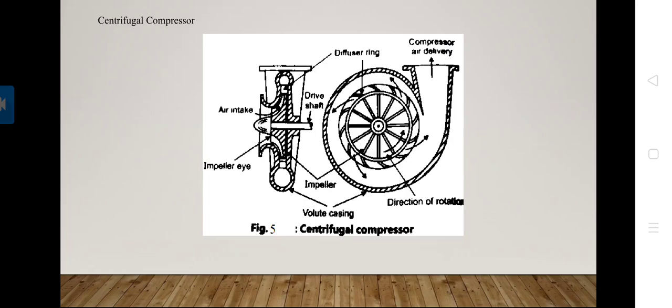This impeller wheel consists of 2 discs, a hub disc and a cover disc, with a number of blades mounted radially between them. The impeller blades are constructed in stainless steel to avoid corrosion and erosion, and an impeller has rotary vanes also, which provide a closed radial passage for the flow of air.